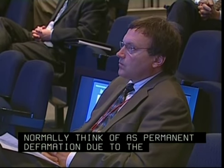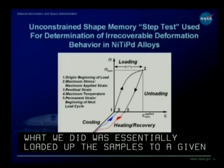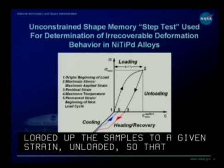And if we have the next slide, what we had to do in order to back out the permanent deformation of the martensite is go through and do these step tests doing shape memory behavior on the material. So what we did was essentially load up the samples to a given strain, unload to say 0.3. We've released the elastic deformation in the material. We then heated the sample up through its transformation temperature. If it came back to the starting point, great. We fully recovered everything. If it didn't come back to the starting point, the difference would be the amount of permanent or irrecoverable deformation that we induced in the martensite itself.